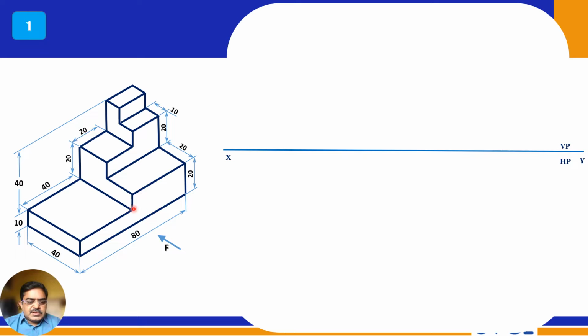And the first step is always front view. You have to draw the front view, and then top view, and then side view. So here the side view possible is the left-hand side view, right? So we have to draw the left side view. First we have to start with the front view.